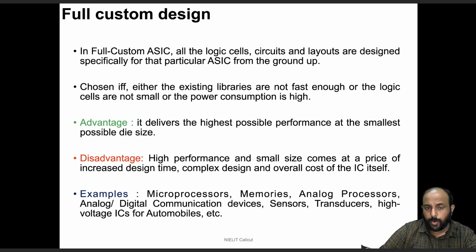First, let us look at what a full custom design is. In a full custom design or full custom ASIC, all the logic cells, including the circuits, the layouts, etc., are designed specifically to target a particular technology node or a particular performance, and everything is built from scratch.